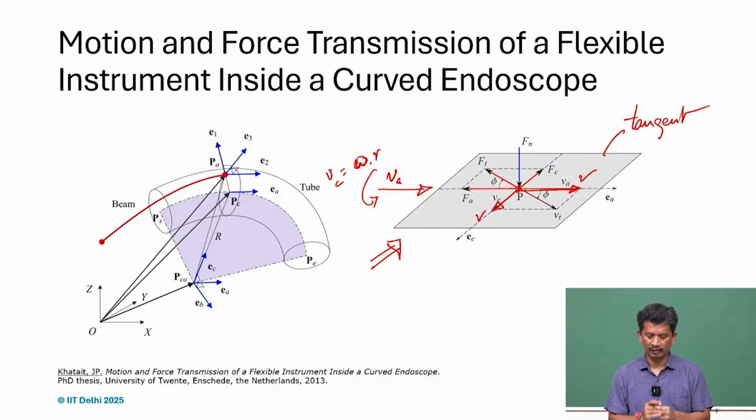If there is no rotation involved, you will have only Va, but when rotation is involved, and Vc is the velocity on the tangent plane, the effective slip velocity will be Vt, and therefore for the friction force, only the direction will change.